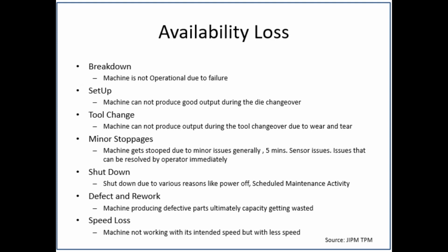Setup loss, again, many times this question is asked. The setup is a very necessary thing to do because we want to have production from one X part to Y part. Then how can one call it a loss? See, the thing is, during setup there is no good product coming out of the machine. That's why it is as good as a loss for the equipment, and that's why it is called a setup loss.